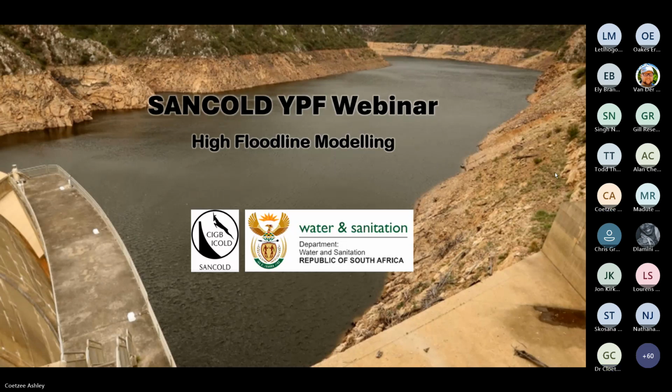Thanks, Brandon and Ernst, for those presentations. Very informative. It's an area I would also still like to get some experience in, the new 2D modeling. Just two questions. The first one is for Brandon. You say you use the bywash spillway, and you use the broad-crested weir equation for that. Does the bywash spillway have a physical broad-crest concrete structure in it, or is it just the channel? Because then I think the broad-crest spillway equation might not be the appropriate one to use.